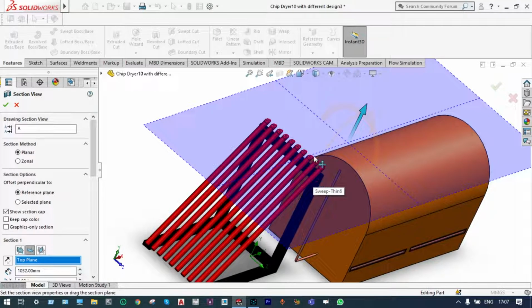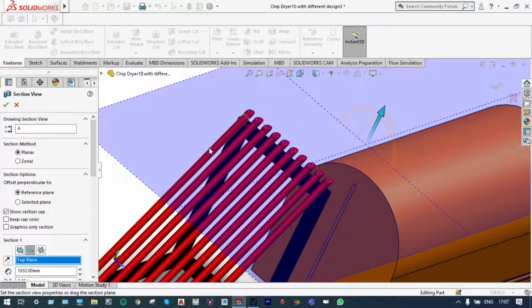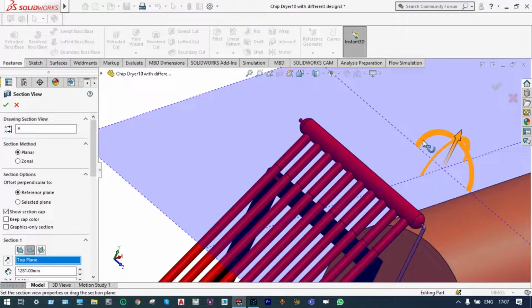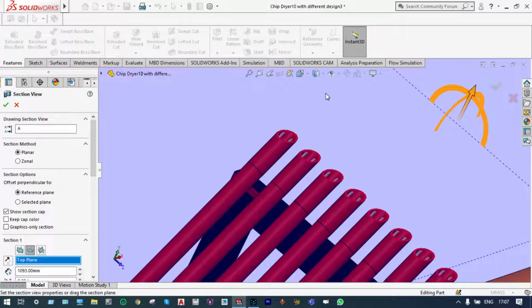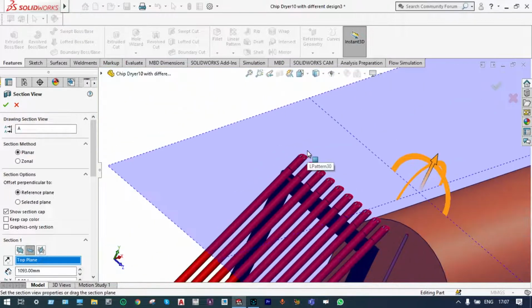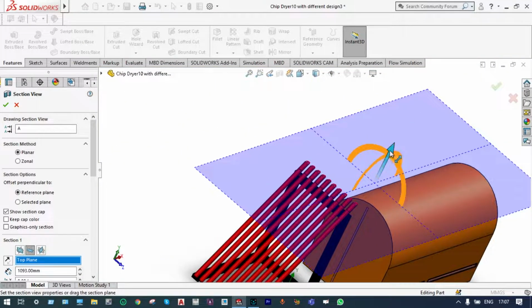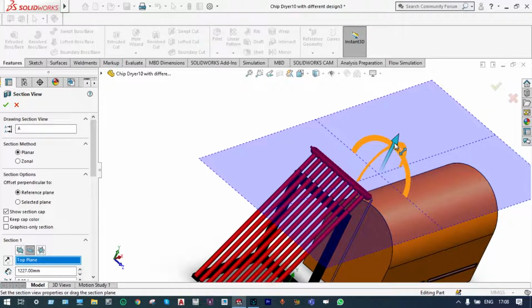And you know that these heat pipes actually have three different types of sections. The bottom part, which is in the form of a U shape, is known as the adiabatic section. Let us drag it and see. From here to the top we have two sections. This part is known as the evaporator, and this part is known as the condenser. Generally, the evaporator will have a higher temperature compared to the condenser. Okay, and let us drag it towards the collector.